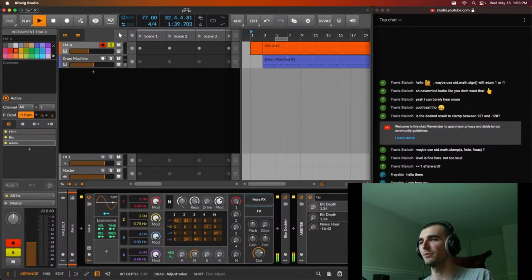So if we go down to like 2-bit, you basically get nothing at 2 bits, and I don't even think we should allow 1 bit, because I think that just produces DC, because you're not getting any polarity, you're not getting actual alternating current. Or we should just throw in a high pass at like 10 hertz so we filter out any DC.